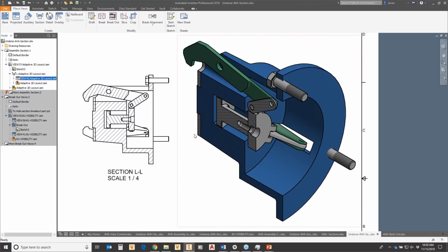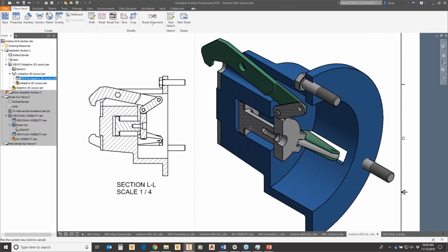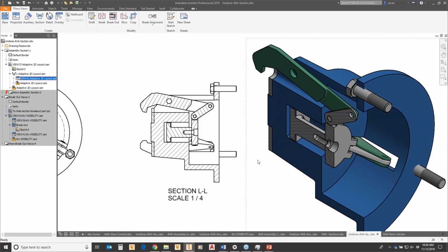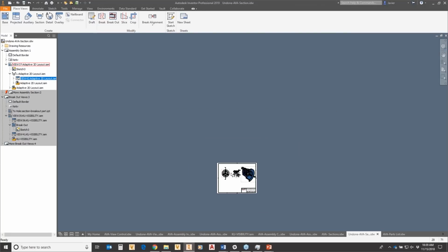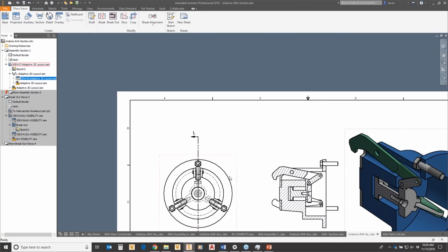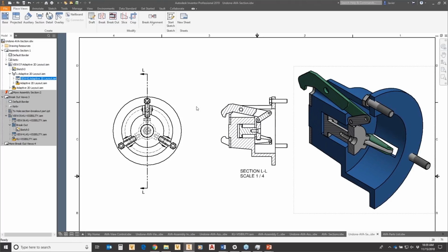If you want a little more control, it makes sense sometimes to show things complete and whole. So while we're doing this, I'm going to change to my part selection mode. Shift right click lets you select objects a little bit differently. I'm going to choose part by part here on the original view, and I'm going to tell it what to section, what not to section.